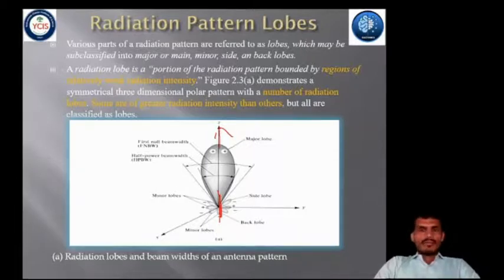Attainment of side lobe levels smaller than minus 30 dB usually requires very careful design and construction. It is usually designed this way in most radar systems, and low side lobe radiation is very important to minimize false target indications. To minimize false target indications, low side lobe ratios are very important.